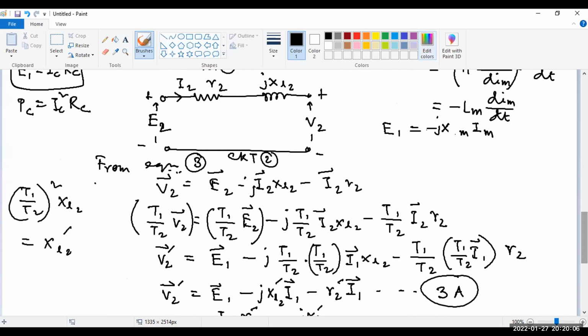Now, what do you think? The resistance that you will get for the primary and the resistance you will get for the secondary, will they be same? Different. Which will be more? Sir, low voltage side, the current will be higher, so lower resistance will be required. Yes, so the high voltage resistance will be more, right? Yes, sir. And low voltage resistance will be less. So how will you ensure that practically?